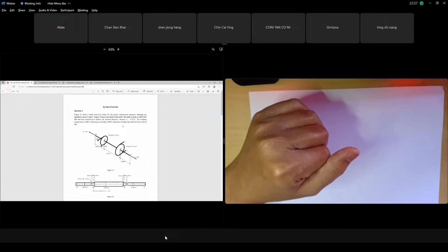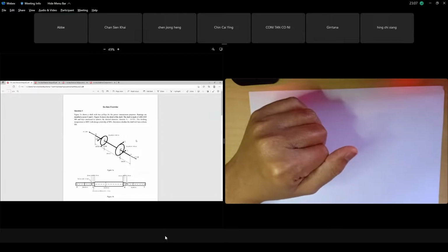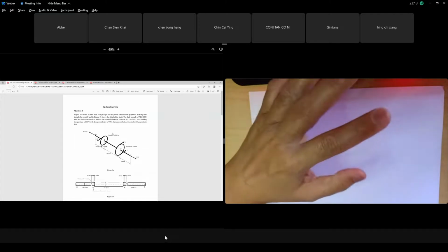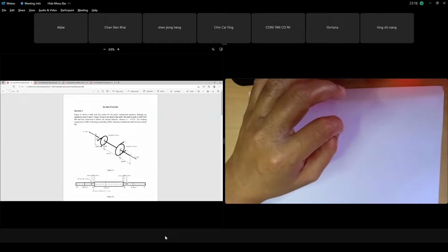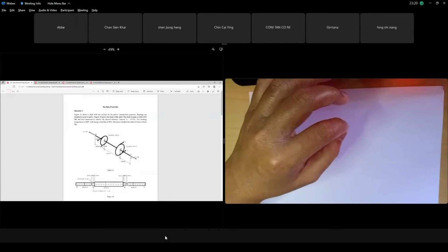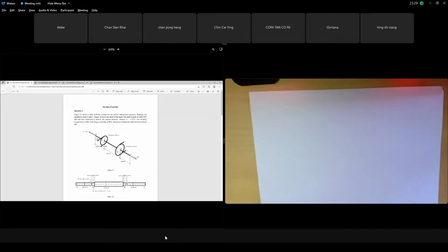the XY plane, right? Because the 2 kilonewton pulley load is in one direction, it's only at one plane, and pulley B also is one direction, only one plane. Let's say X, Y, Z. So it's pointing in Y, both are Y. So our plane is only one plane, the XY plane. We don't have the other plane. Along the shaft is the X direction. This shaft is O, A, B, C. O and C are bearings, support bearings at both ends, O and C, and at A and B are pulleys.